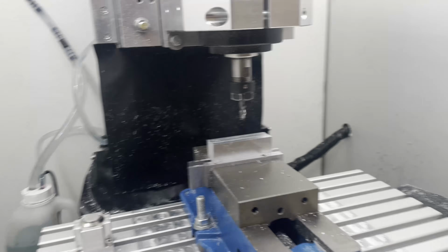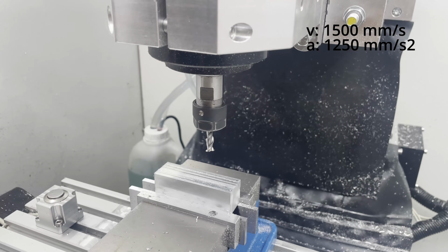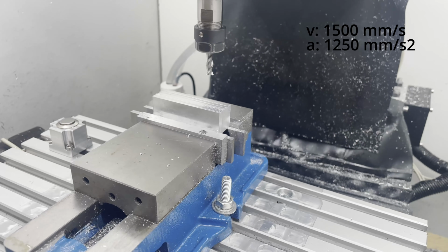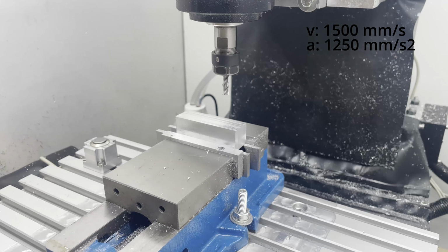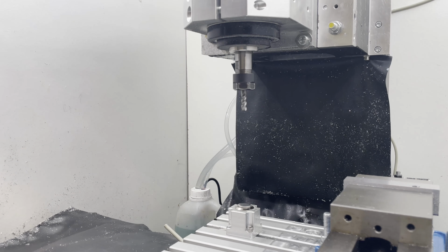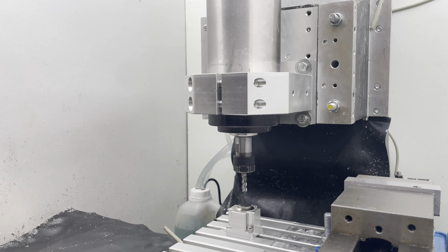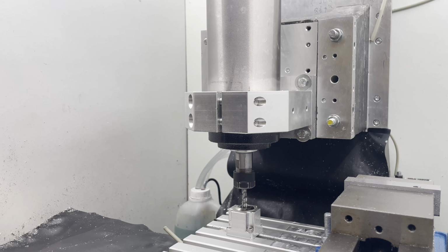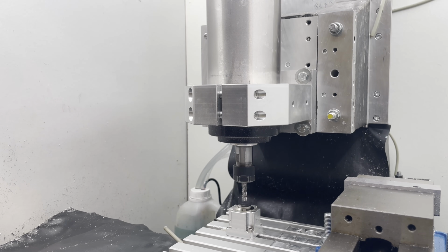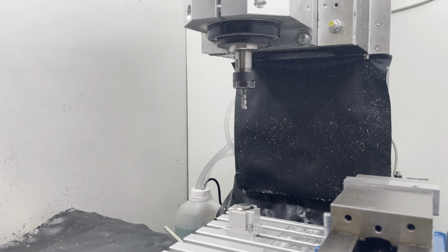For the acceleration, I did some trial and error tests to see how high I can go, and now feel quite comfortable with around 1250 millimeters per second squared, which seems to be no issue, and the feed rate here is set to 1500 millimeters per minute. This is the most I would feel comfortable with right now doing an actual cutting sequence. Maybe if I know the program well enough, I will override it a bit closer to the 2000 millimeters per minute. This would mean an increase of both acceleration and normal feed rate of about 200%.